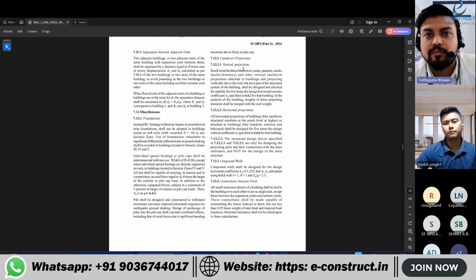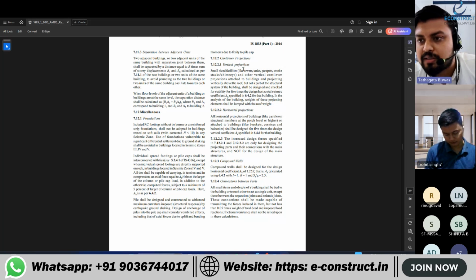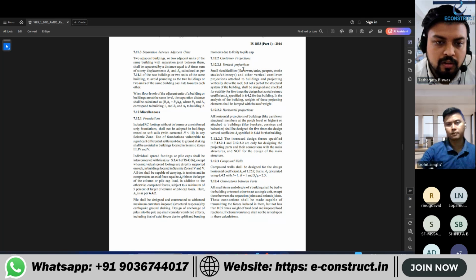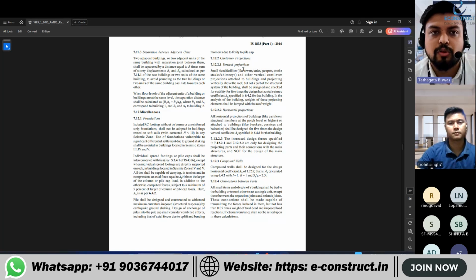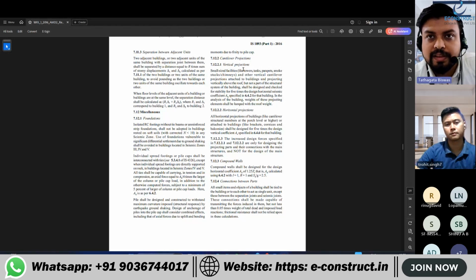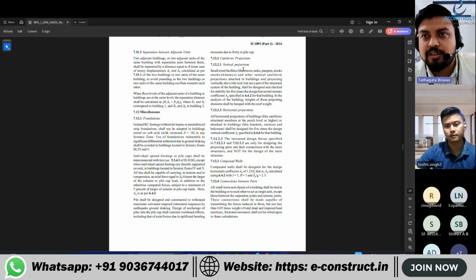But the problem is that the brick and block property is not fixed during the time of design. It gets fixed much later, once the site is commenced and procurement gets started. So the exact property of that particular material is very difficult to get. That's why we just follow the density, calculate the load and put it on the beam. We couldn't model that because of that property issue, because masonry property is there in ETABS, but that masonry property